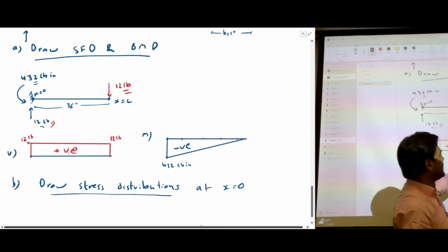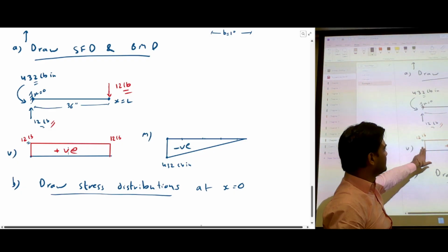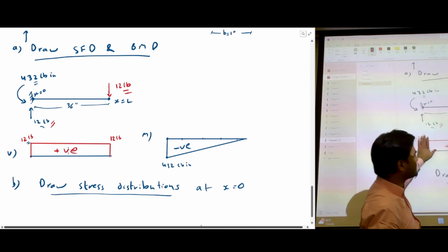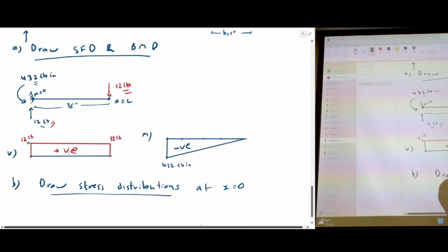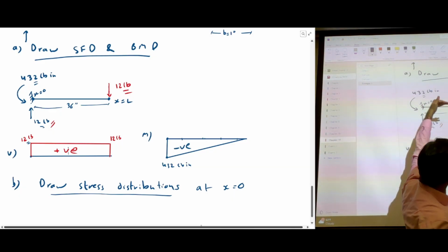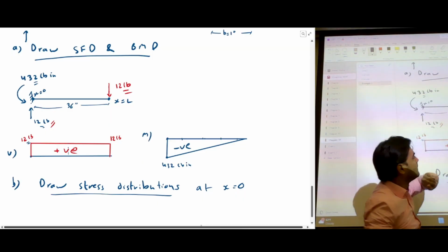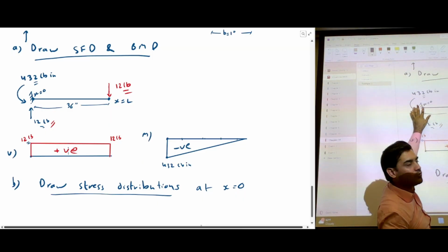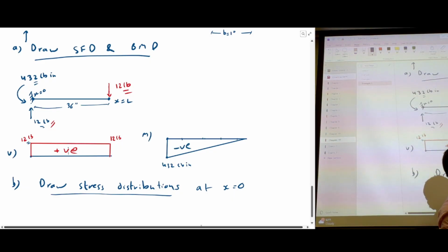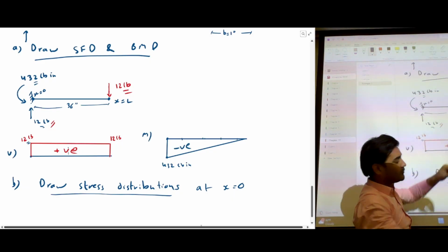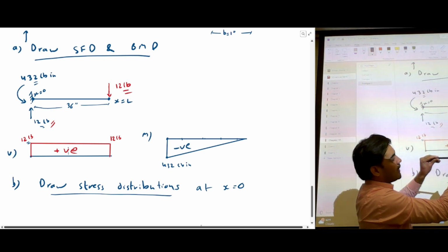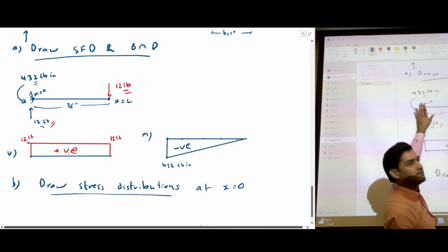From the shear force and bending moment diagrams, we can see that the shear force is constant along the length, but the bending moment is highest at the start, and as you go away from the fixed support, you see decreasing bending moment. If you keep increasing the load, it keeps bending and it will break at this point due to bending moment. If you try to pull a cantilever beam at the end, it will always break at the starting point.